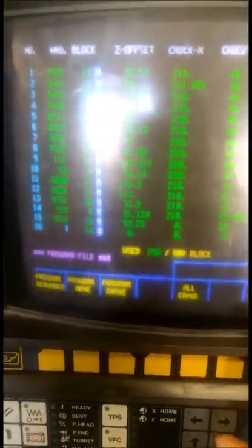So that's just a quick little check to make sure all your tool paths are alright. That'll bring up errors if you've done something wrong, and if anything's glaringly obvious, you'll see it there. In program file is where your Z offset is. So we'll go down to work number 1, which is the program we just made, and from default the Z offset's just 0.